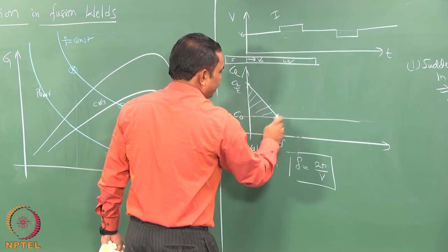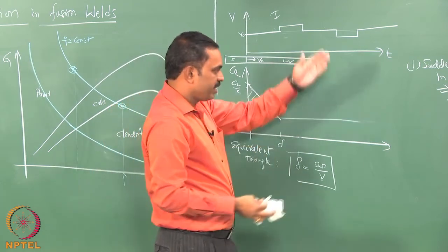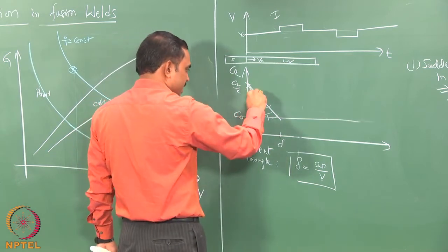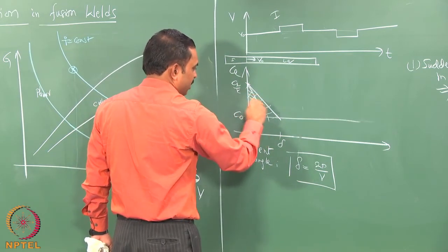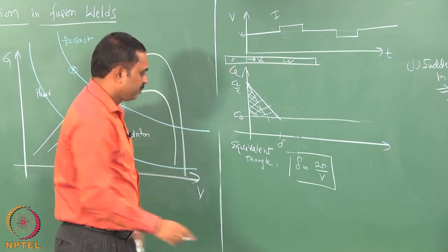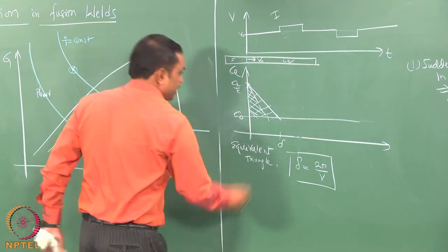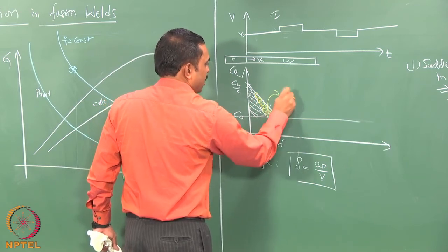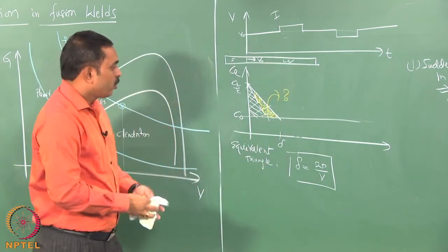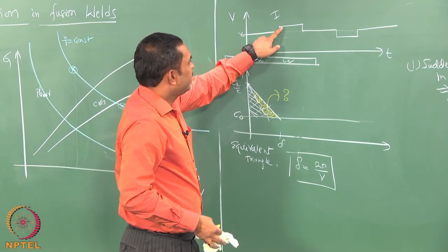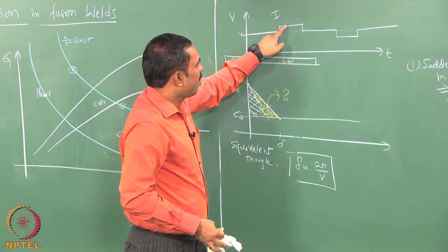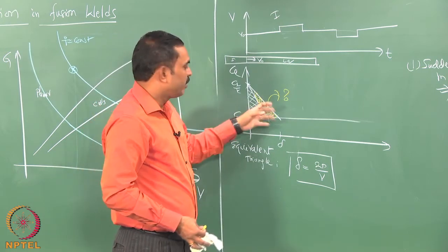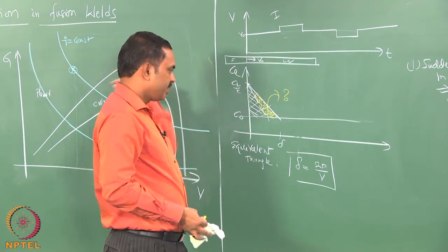This is the amount of solute you are supposed to have, and suddenly when V is increasing you are supposed to have a lower delta, which means that this is the amount of solute that it can take. And what can happen to the rest, this region, where will it go? In order that at an increased velocity also you again have a steady state for a long duration, this excess solute has to be dumped in the solidification that is happening behind.